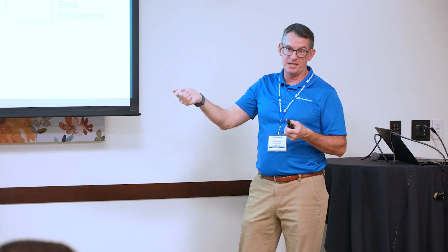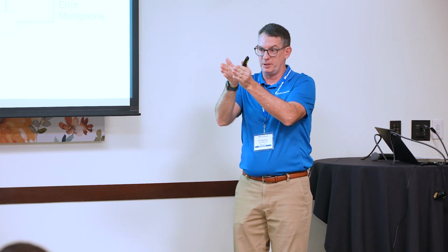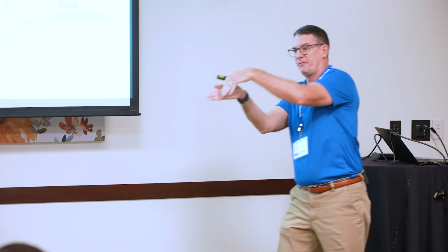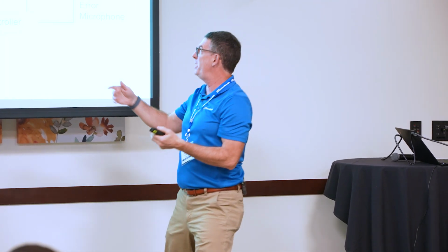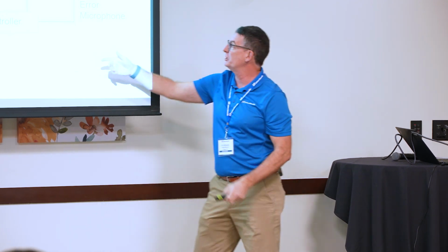The higher the frequency, the shorter the wavelength, the more likely that sound is to not just go straight down the ductwork, but to take some angle and bounce off the duct walls and do the things that make it be controlled well by insulation.